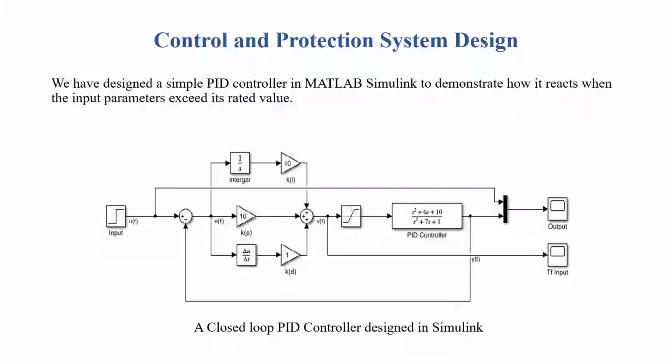As per the diagram, a closed-loop PID controller has been designed in Simulink. The summation block senses both input and output signals. This block continuously monitors the output parameters with its reference value. As per the settings, when the parameters deviate from their original rating, the proportional, integral, and derivative blocks rectify the input values accordingly and provide an output signal so the turbine can operate in its safe range.